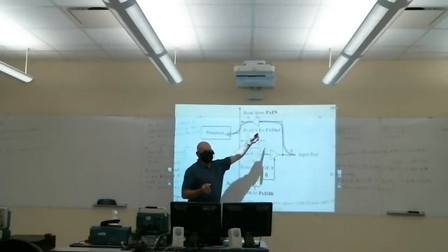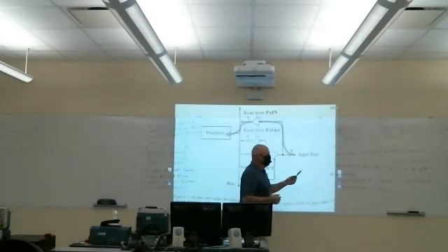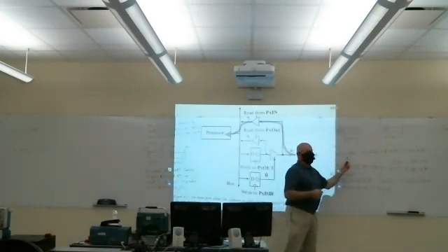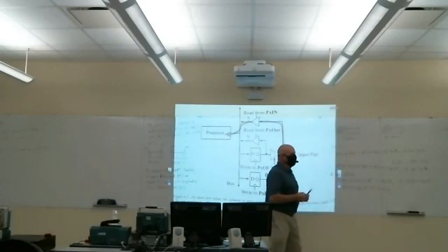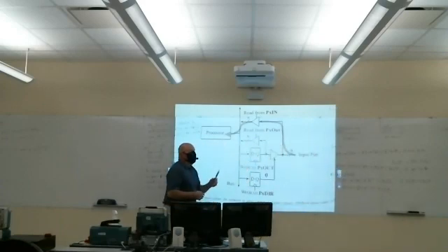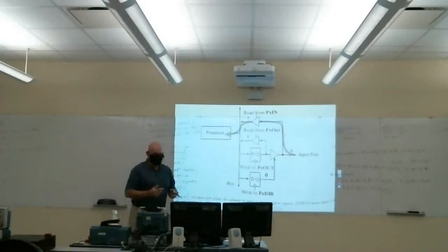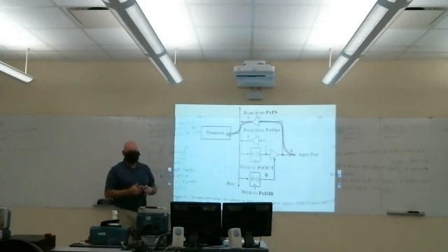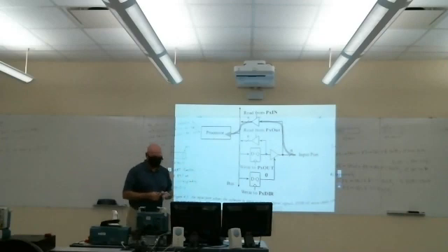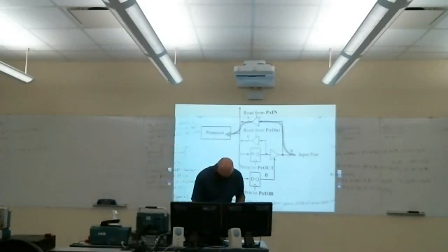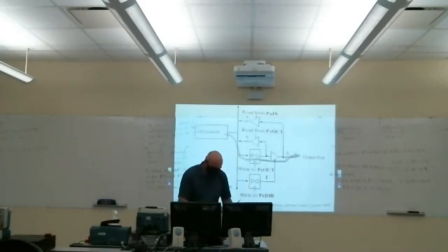Again, each port will have a corresponding input register. We'd have to read from the P9 input register, just like this, except it would be PN, P9, and then an arrow in instead of the selection register, to read that corresponding bit value. And then we can see if it's a 1 or 0. Okay. Any questions there? So we read from the port input register to read input values.